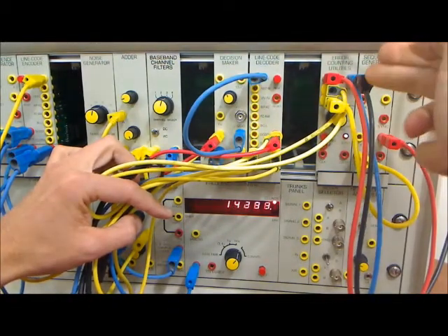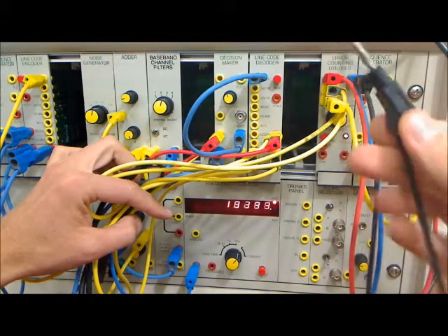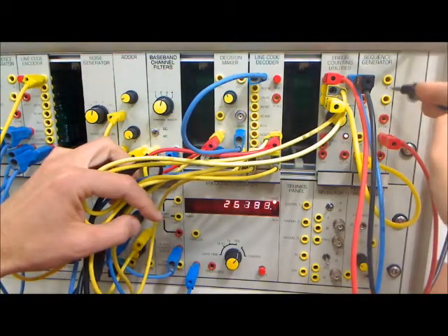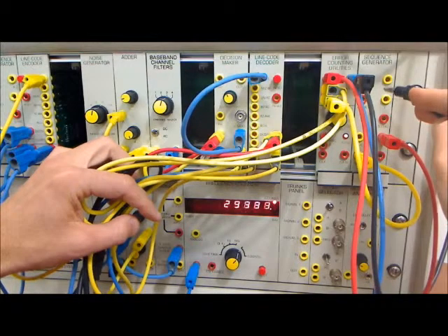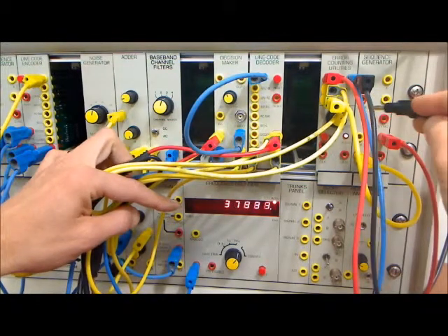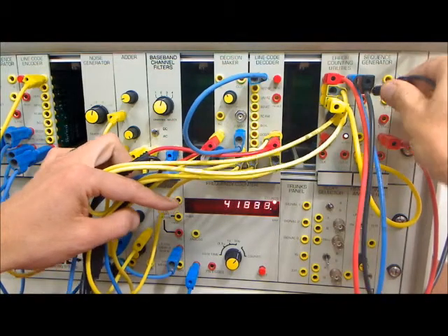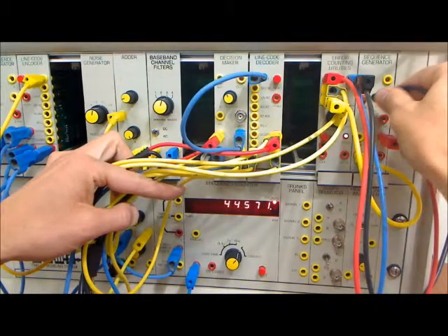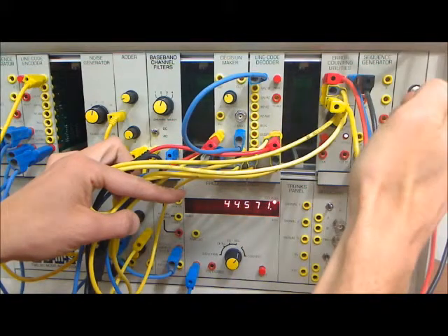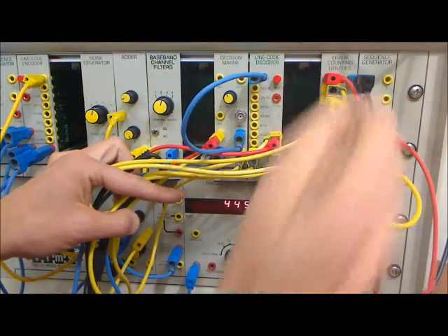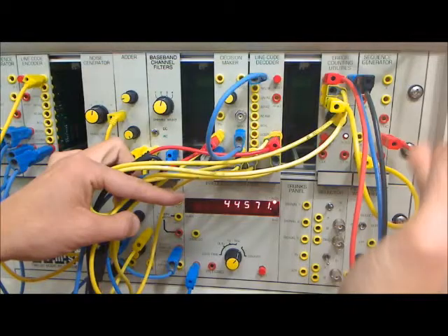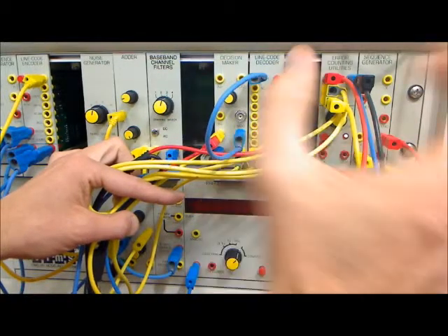We now take the same error pulse stream and, on the black lead, we put this error stream into the sequence generator's reset input. It'll cause the local generator to slide, like a sliding window correlator, until it matches the received data stream. I'm about to connect to the reset pulse, and there you go. You can see the errors have stopped accumulating. There are no more errors, it's not incrementing, which basically means the recovered sequence with no errors is now exactly the same and aligned with the local sequence.